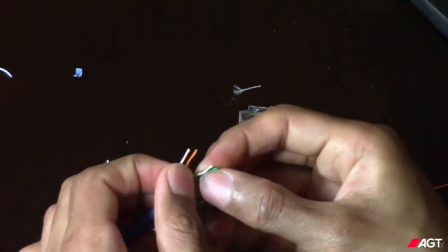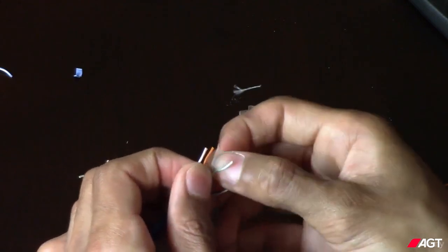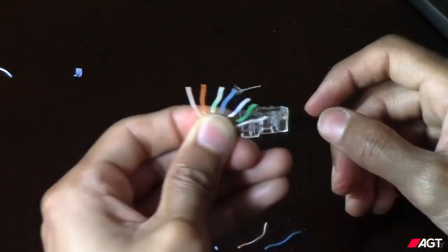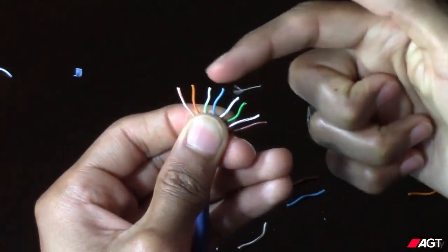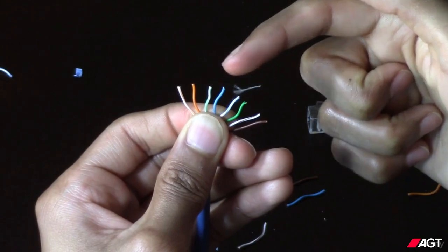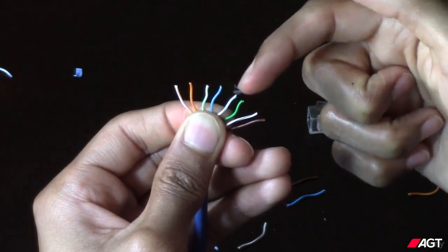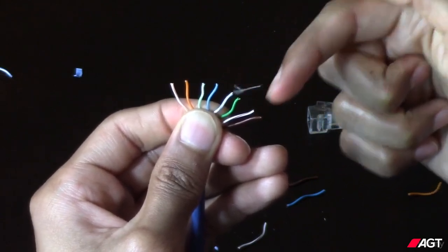Just like with the jacks, there are 2 different patterns you can opt for. Neither is better than the other. For this video, I'll be creating connectors using the B pattern, which is orange-white, orange, white-green, blue, white-blue, green, white-brown,